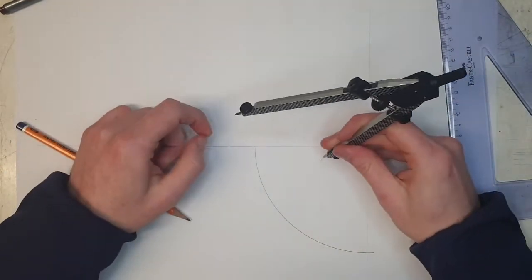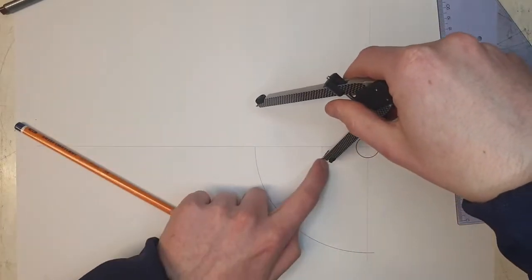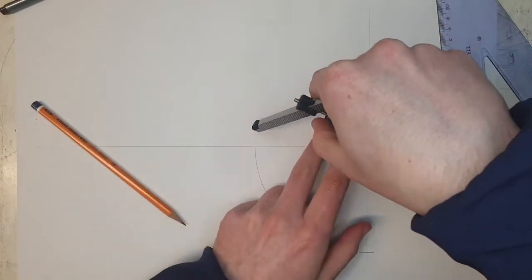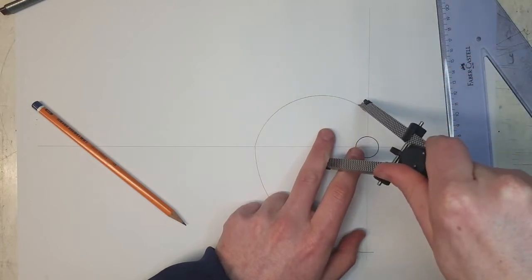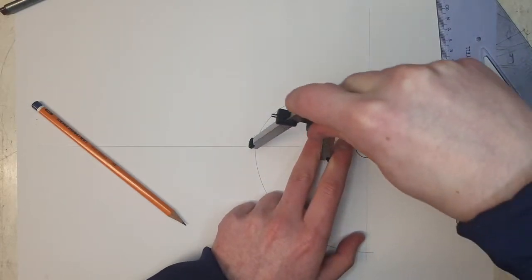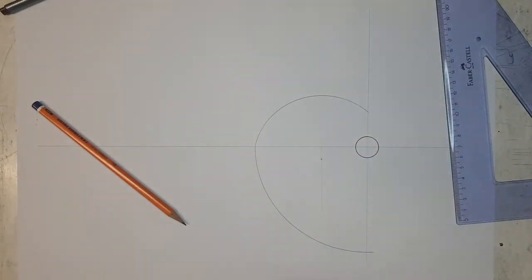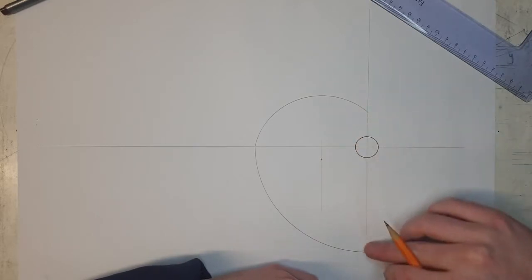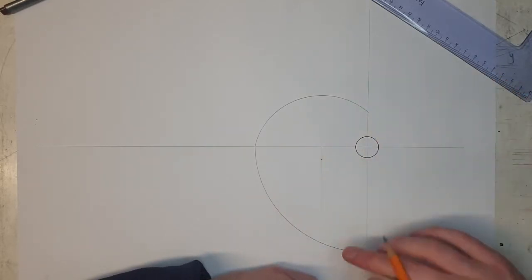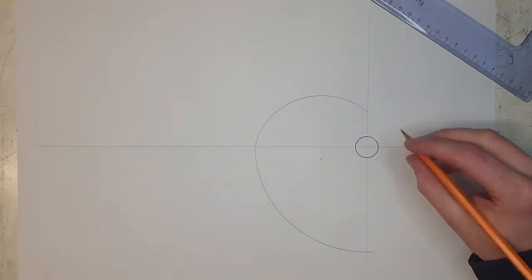And we can put the point of our compass there, and it just says R, so it's not a given radius, but we know that the center of it is here, and it goes out to this point here. So I'm just going to measure out to there, and I'm going to swing it around until it hits here. So that's as much of the cam that we can draw at the moment. We're not given dimensions for this side, but we're told that it's a simple harmonic motion, so we're going to have to do a bit more work before we can draw that in.